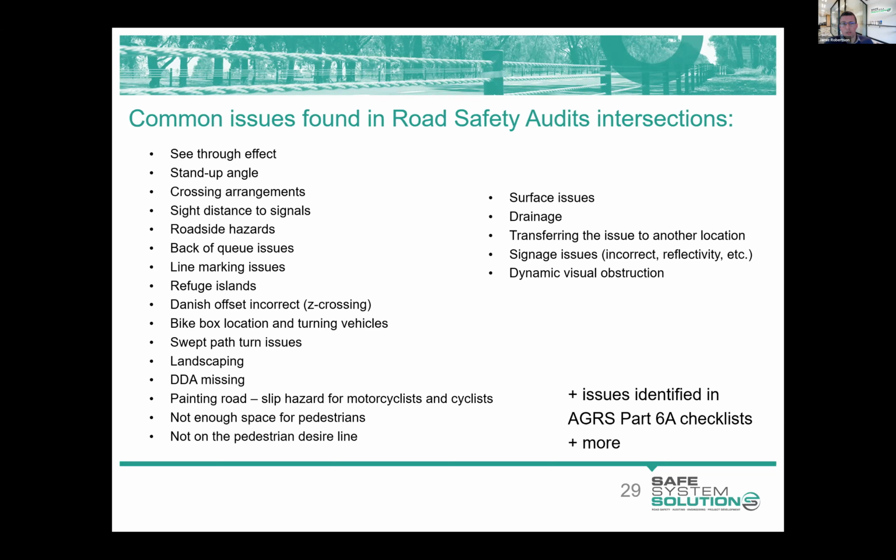So often at intersections, you can also see back of queue issues on freeways, major roads where you've got turbulence maybe in the vicinity of an entry ramp or a weave or something, and you see some flow breakdown. They're freeways. You don't expect to encounter a queue, and we do see some serious back of queue issues on those types of roads,